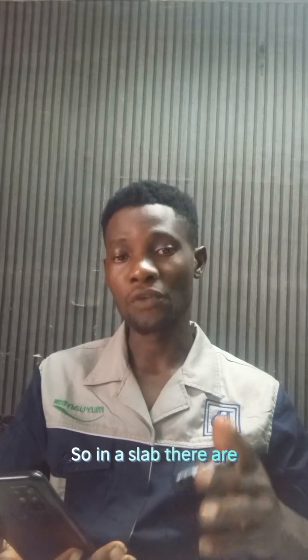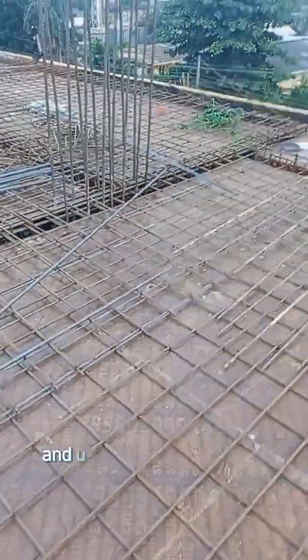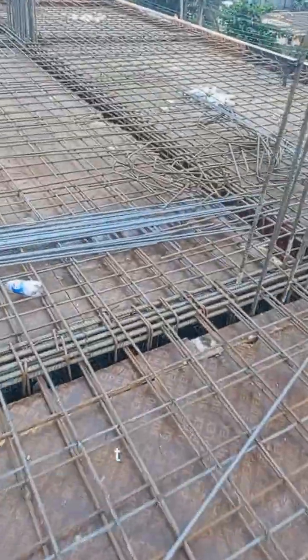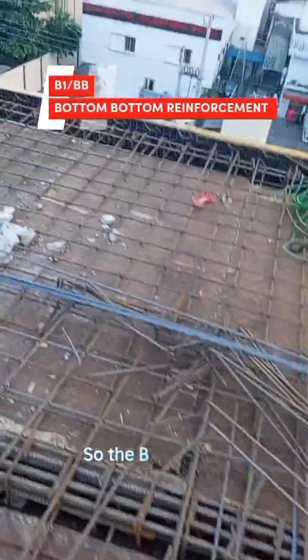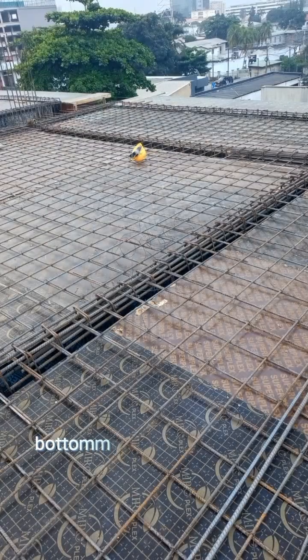So in a slab, there are 4 different layers of reinforcement. Those reinforcements are the ones that are given those names. I'll explain it in this video and use a structural drawing to explain how these reinforcements are arranged. So the B1 can also be called BB, that is bottom reinforcement. The bottommost reinforcement in a slab is called the B1 or the BB, that is bottom reinforcement.